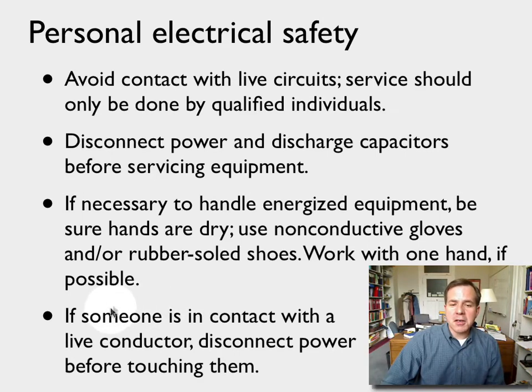Finally, as I mentioned earlier, if someone is in contact with a live conductor and is being electrocuted, it's extremely important that you shut off the power first before attempting to help that person. If you touch a person who's being electrocuted, it's possible for you to become part of the conductive path and be electrocuted yourself.